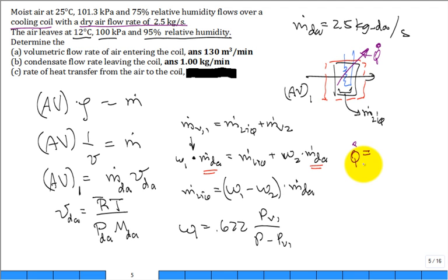Do it in components. One component would be how much to cool the dry air. Well, three components. Mass flow rate of the dry air times the enthalpy, inlet minus exit, will give the rate for the dry air because I want a positive Q dot out. And then we're going to do the mass flow rate of the vapor that exits, and then we'll do the mass flow rate of the liquid.